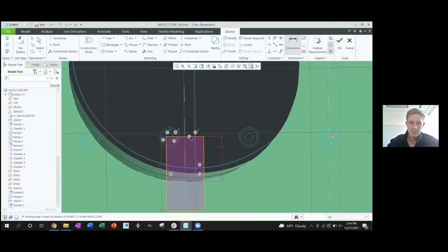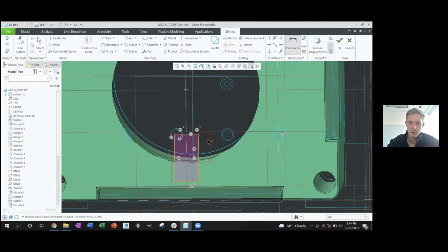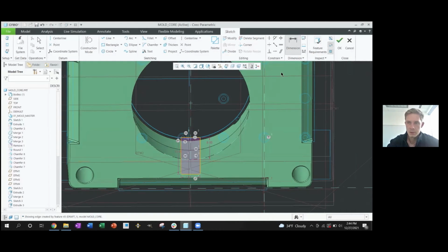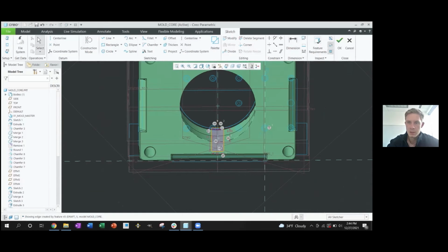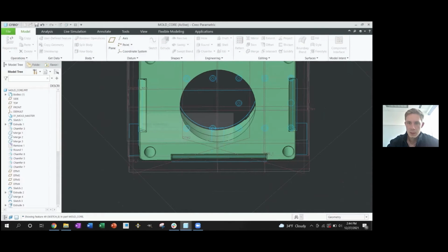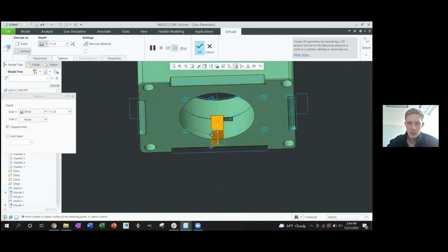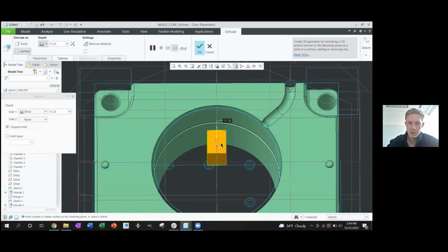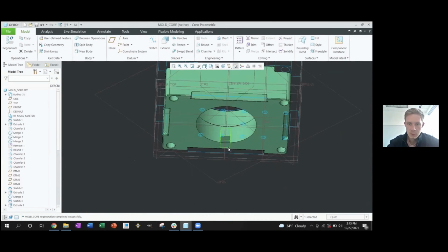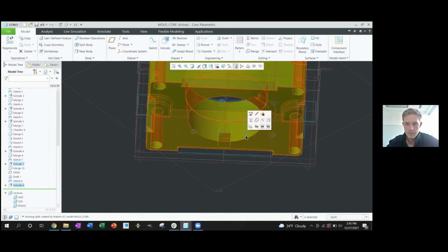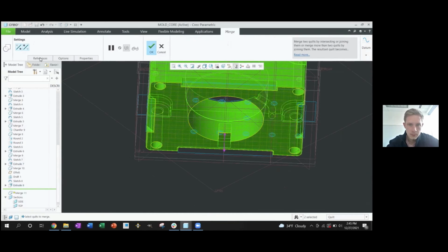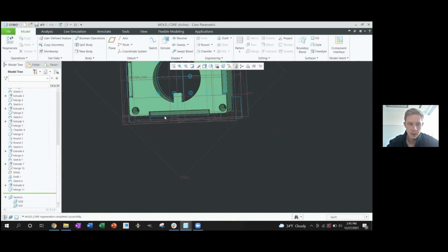We don't need to have a tight fit between the face here and the actual insert itself. So we're going to leave a whole millimeter of clearance there so that we don't run into any sort of interference issues. In a similar fashion, we're not trying to constrain the height, we're just trying to constrain the rotation. So instead of an 8mm extrusion, we'll go with 7mm, so we leave ourselves with some extra space. Go ahead and merge these two together. Perfect. So we have our key feature.